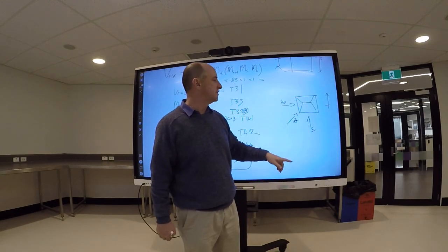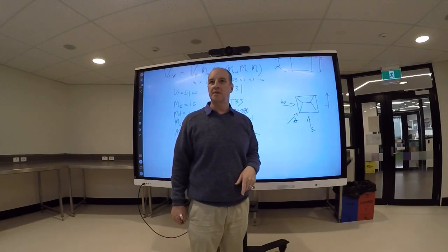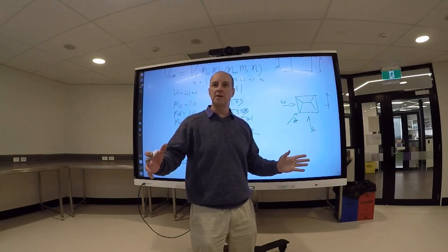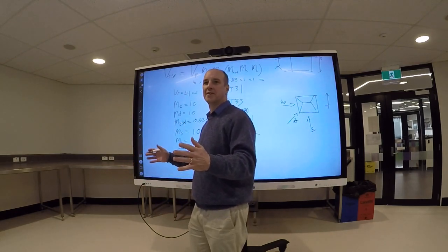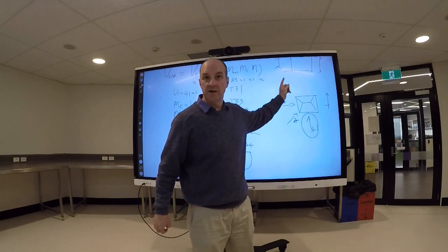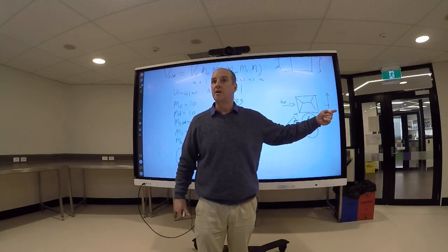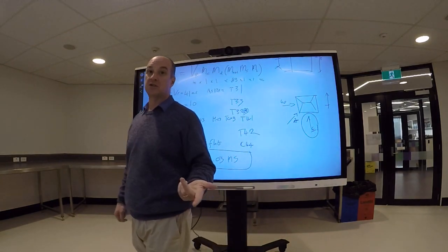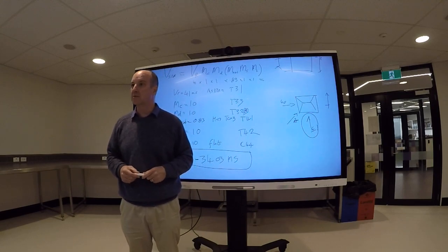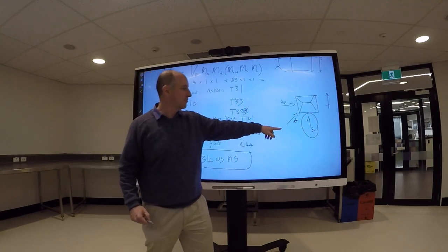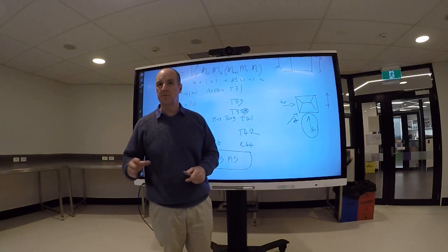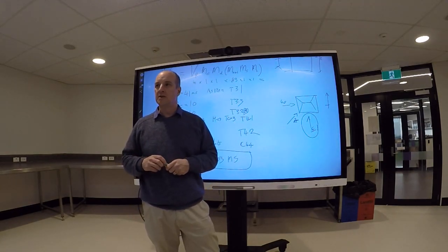Quite often I say to myself, this building that I'm designing, I'm not confident that at a late stage the architect is not going to say, you know what, let's have it this way around. So the conservative thing to do is to pick the worst one and design that all the way around. Be careful with always taking the conservative option, because those conservative things add up until you've very over-designed something. But that one, you're definitely going to sleep at night. Does that make sense about conservatism? Yeah. Okay.